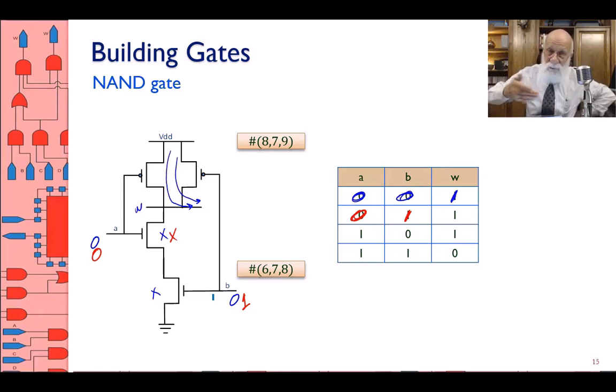We are talking about NMOS transistor pushing a 0 to the output, PMOS transistor pushing a 1 to the output, and therefore a 1 on the B causes a push of 0 from the ground side of the lower NMOS transistor to the output side of it. But then when it reaches the A transistor, it's blocked. The 0 is as far as it goes, it just blocks there.